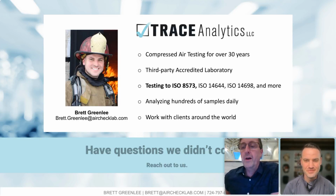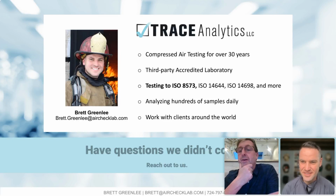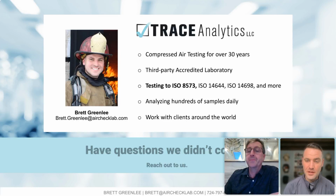Well, on that note, there is another question. Although we've wrapped up, we will take it. Priyanka asks, how do you test the microbial quality of compressed air in-house? If you have an in-house micro lab, we have seen this before. We offer impaction sampler equipment, and impaction samplers are the only ISO 8573 accepted method for testing microbes.